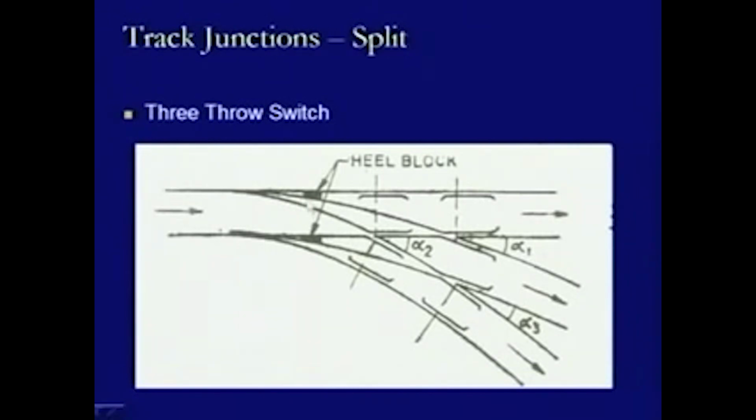So this distance block will also come up to this location and will connect like this, so that it remains in position. And there is an extra safety measure here, because we are providing one wing rail at this location, therefore the check rail has to be provided at this location opposite to it. Whereas again, because we are having two more crossings provided here, they are just coming overlapping each other in a similar position because of the type of curvature being provided. So here also we will have a check rail provided here and at this location.